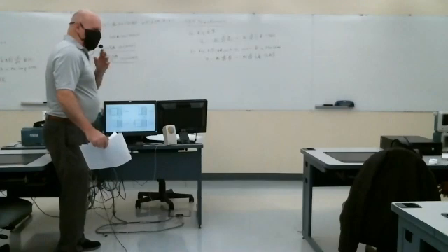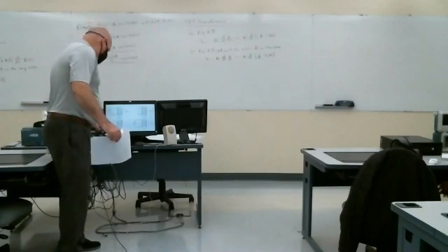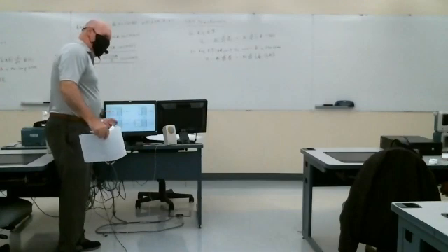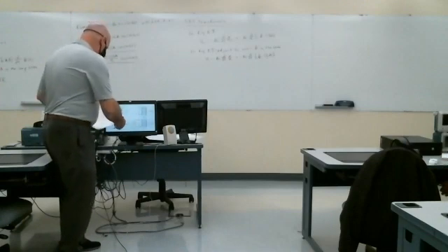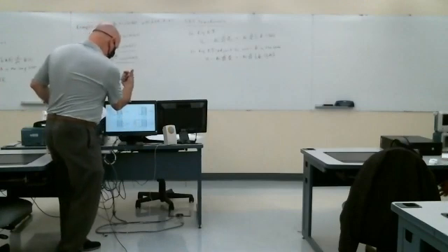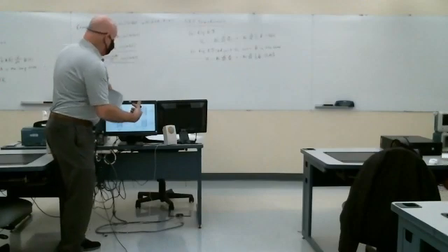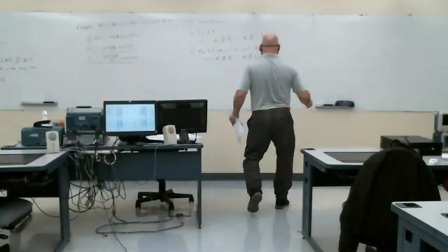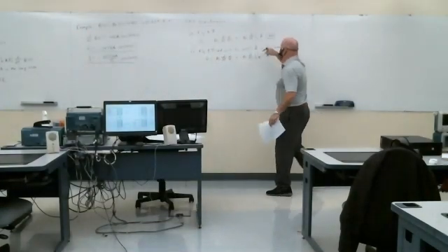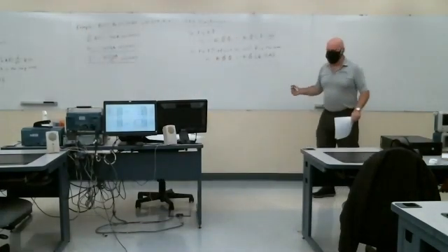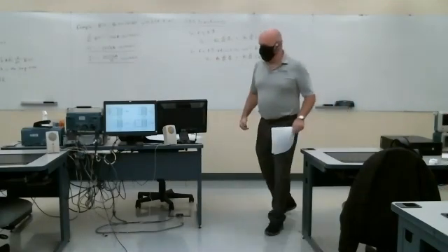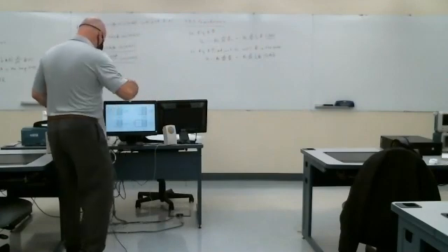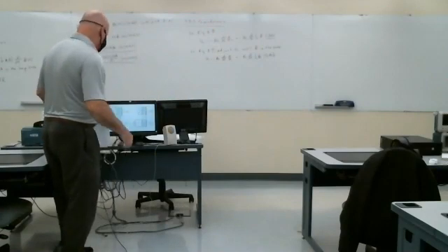In the second coil, that's where we have our voltage induced, and so my current actually flows into the minus terminal, around the loops, and out the plus terminal. So when I do that, the surface area would be negative Z directed, like this. And I haven't taken into account the B field. If V1 is positive, it would also be minus Z directed.